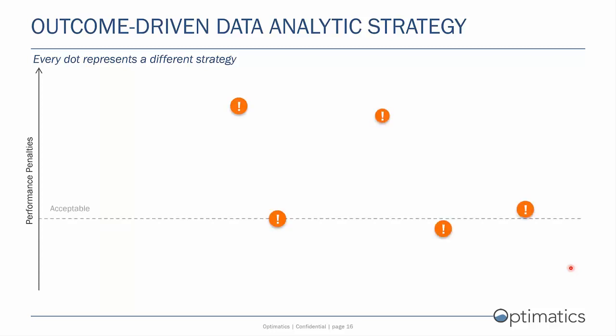So in my 30-year growth projection, I can see that my current network is not able to meet my required performance standards. And I can see that in my WS Pro model in terms of my minimum pressure requirement, and I've mapped my performance here along a y-axis. So we can think about performance with plotted them here as performance penalties.